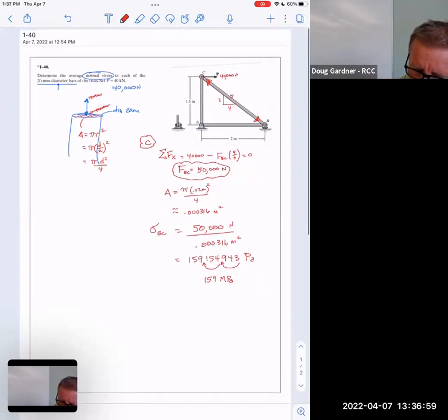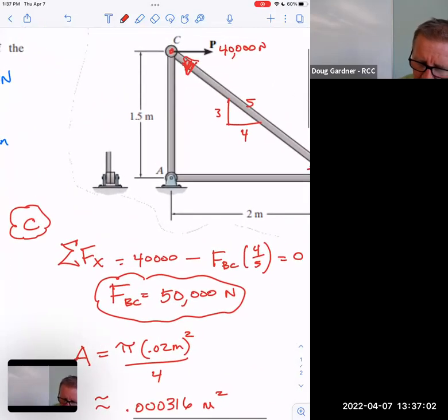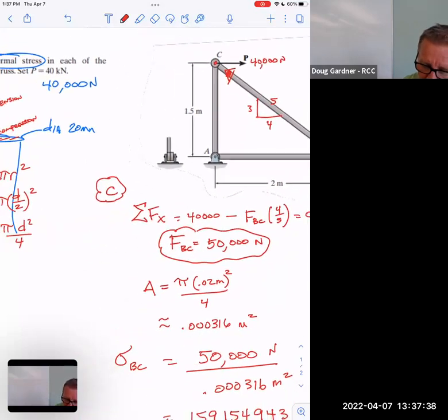Well, this is what I find so interesting about this. If I go back and erase this for a second, does it make sense there's no force on AC? There's no force on that at all because that force is sideways, right? And yet, to balance it vertically, we had to have a force there, which now means there is a force upwards. You see what I'm saying? My first thought could be no force on AC, so there's no stress. That could just be a piece of string. No, that other force over there resulted in an upward force. And so now there is a sum of the forces in Y.